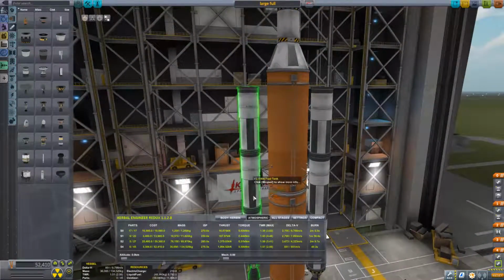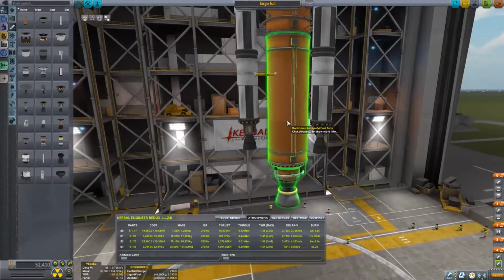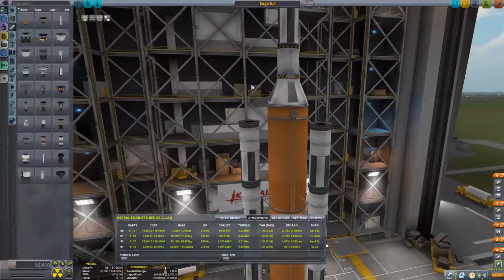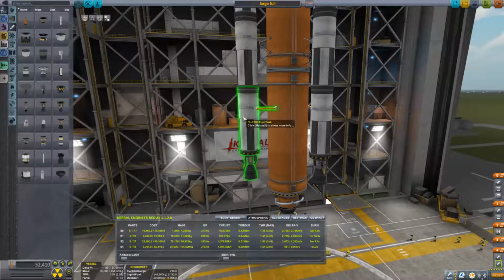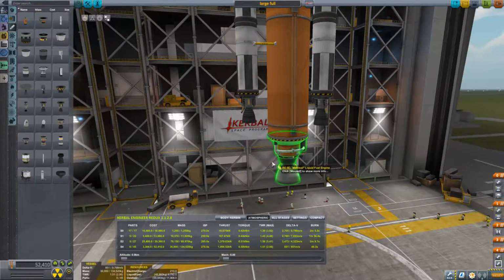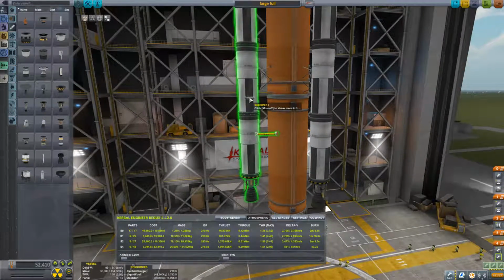The first stage is now this side stage though, and it will get up to 851 meters per second of delta V. We drop that guy off, and this whole center section is full. Now the disadvantage here is there's more things on the outside that cause drag, and if you drop the outer stage off and it falls inward and hits the engine down here, it could cause that to explode. There's ways of dealing with that, like adding these little separatrons.